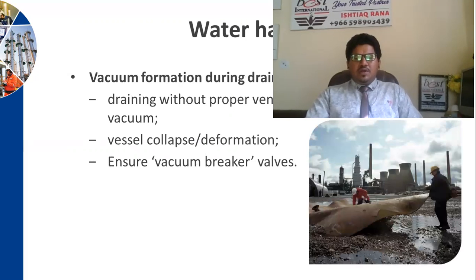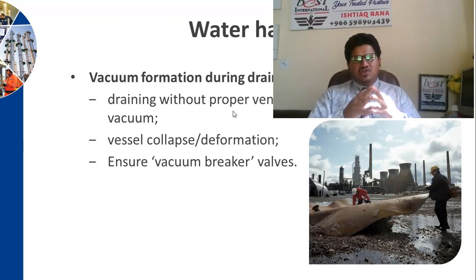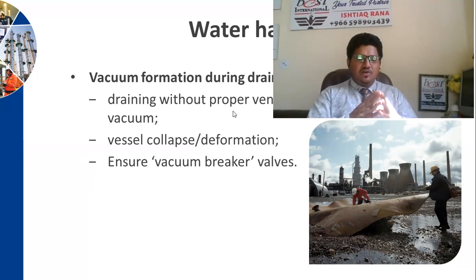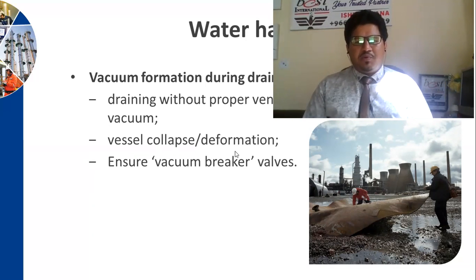Vacuum formation during draining operations: draining without proper venting can create partial vacuum. So what is proper venting? Just start searching. I'm telling you, some of the better hobbies you need to develop as a passionate learner. Vessel collapse, deformation: ensure vacuum breakers are there.